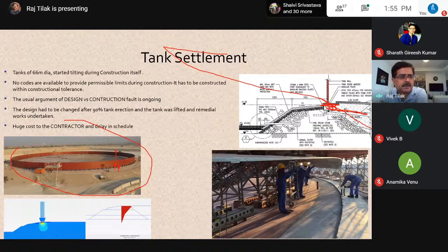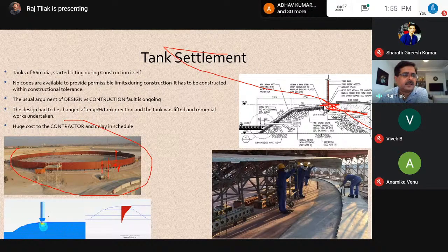So be aware, and for those who are interested in design and engineering, you can decide what model should be best if you're analyzing in Plaxis, whether 2D or 3D. You can see that I probably had adopted 2D. Why not 3D? Because if you look at the tank size, it's too much, and I am just analyzing a section of it, and it's a plane strain case for the foundations. So this is the amount of tilt that I got with the given loading conditions.